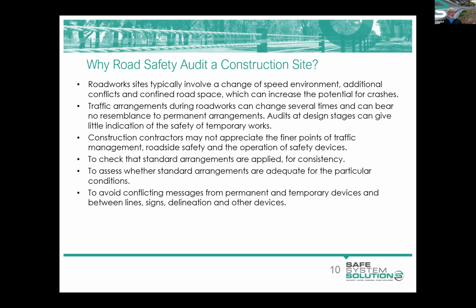Oftentimes you'll just see black paint put down, but in the wet or at night under headlights, that black paint can shine up as if it's a dull line marking. So it's best to grind that line marking off and start again with the fresh lines that you want to work under. So it's important that those temporary arrangements are removed, so there's no ghosting at all.